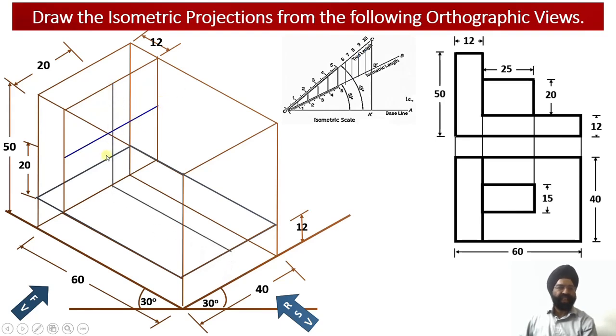Please check, this is my center line. Having marked the center line, an offset of 7.5 millimeter on the left side and 7.5 millimeter on the right hand side has been marked. This gives me the thickness of the web. Please check, this is the width, or the thickness, of the web. So I have been able to locate the width of the web, which is located centrally.